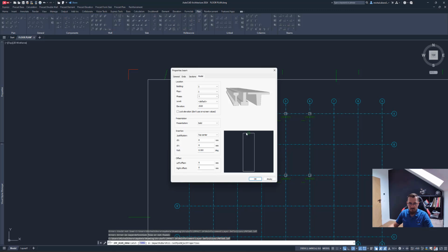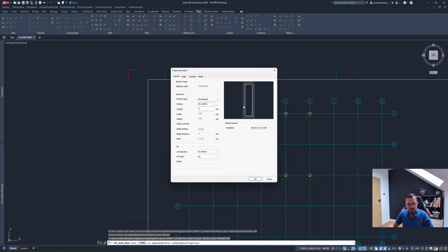As you can see in the preview, this is my alignment point, or rather my insertion point. I want to lock the elevation, because we are working in a 3D model. It's easier to lock the elevation to a specific point if we're placing horizontal elements, so we know we are keeping that elevation. Sometimes we can snap with AutoCAD to some point that we don't really mean to, and then it will be at an angle or placed very weirdly, or not exactly how we want. So it's worthwhile to do that. Let's go to 6000, and that should be it for the placement of those columns.